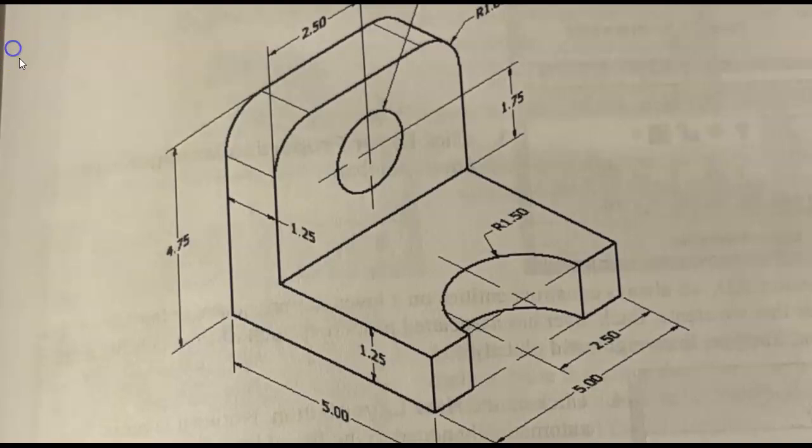I'm going to go up to my line tool to start. Now, notice as we're in this particular line tool, it's given us a specify first point. You'll notice we can't do a whole number in the X, but it is giving us whole numbers in the Y. So it doesn't necessarily matter. I just want you to pay attention to that as we go. We're going to be entering the actual numeric values here when we go.